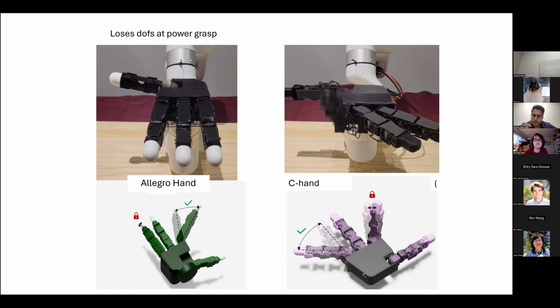And because the hand is completely rigid, you can easily model it in simulation. So there's this open source specification of the hand, which you can put inside a simulator and train with large scale RL. As an illustration, we train this in-hand cube rotation policy. And the interesting thing is because it's trained with learning and it gets a history of joint angles, it can implicitly estimate the state of the cube. So there is no perception. It just uses a history of joint angles to estimate the state of the cube.